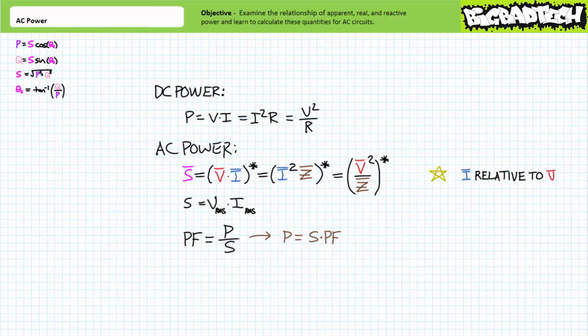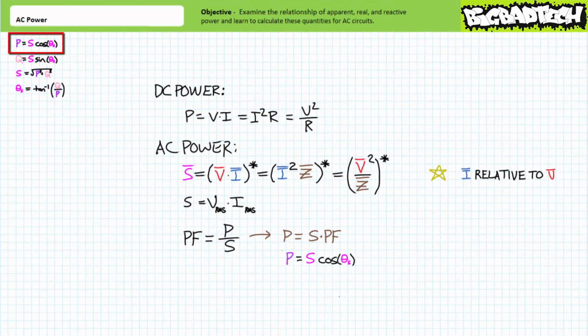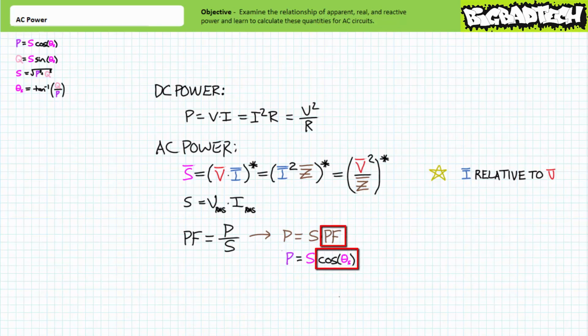As we demonstrated, real power equals apparent power magnitude times power factor. Given we previously illustrated how to convert complex numbers from polar format to rectangular format and vice versa, it should be evident that power factor is a pre-calculated stand-in for the cosine of the apparent power angle when apparent power is represented as a complex number.